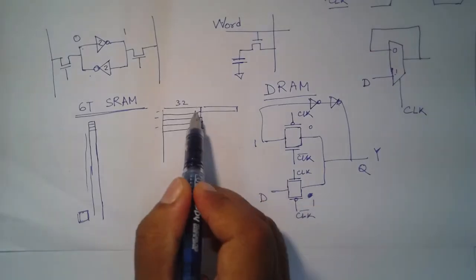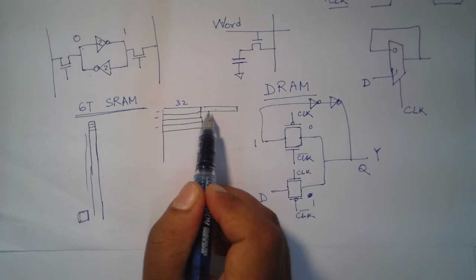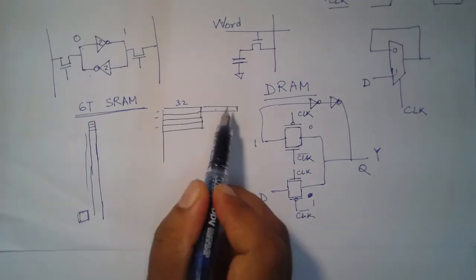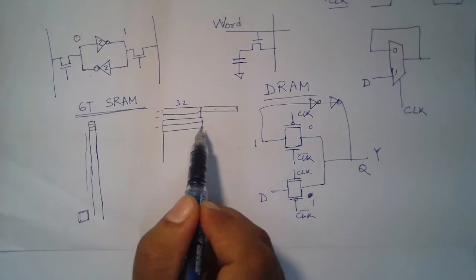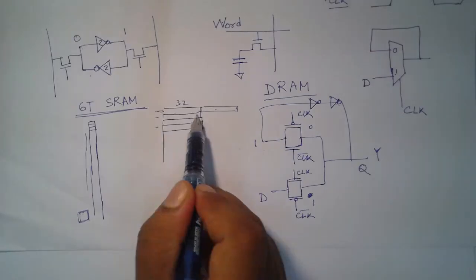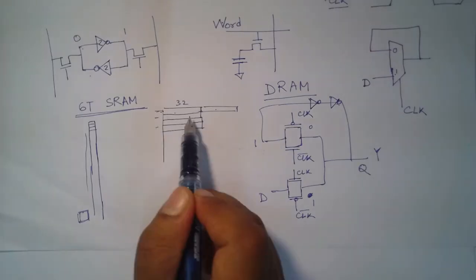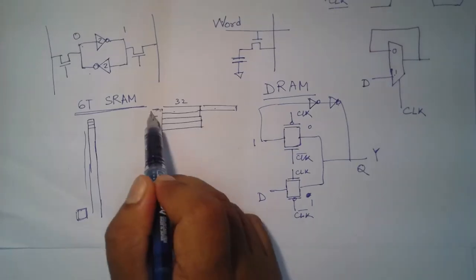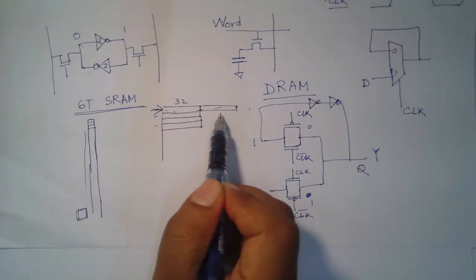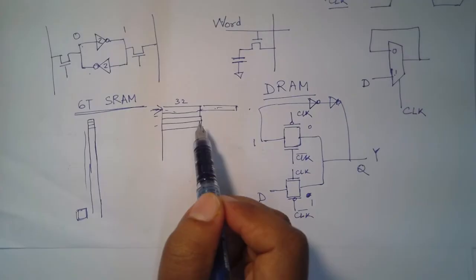Now when you do that, this is fine, but your row decoding now becomes a little more involved, because it is no longer like one address specifying one word and you get that value. Now the same address, this same row, has multiple words. So now which word you need to select, you have to have that additional information.